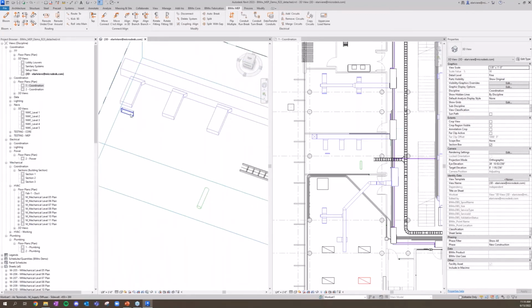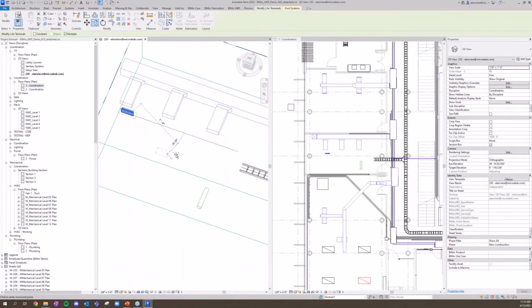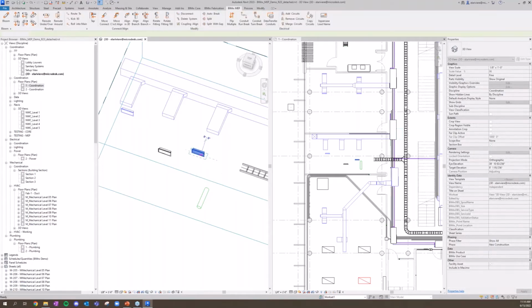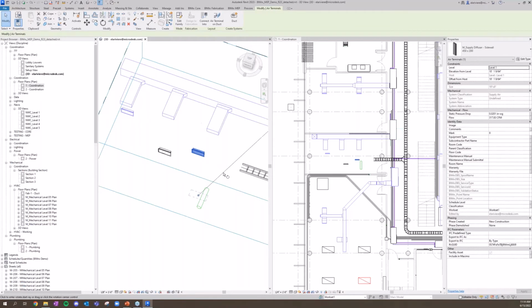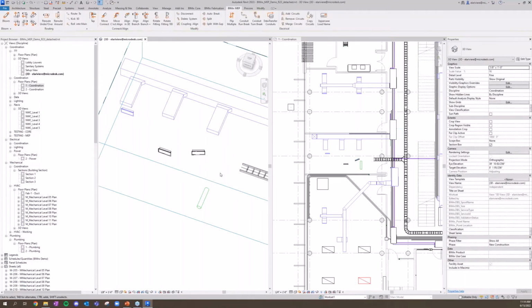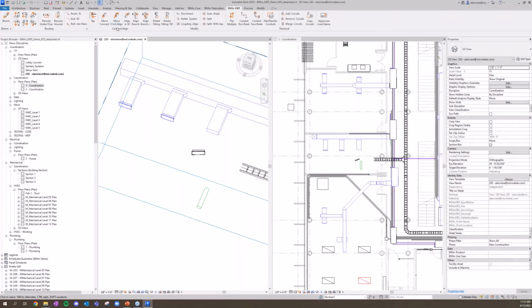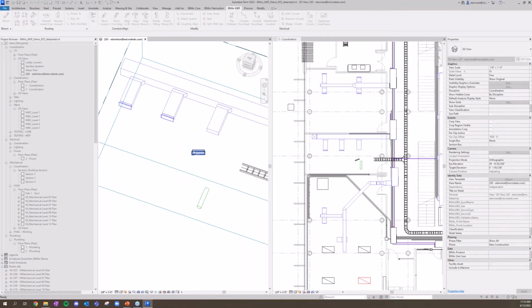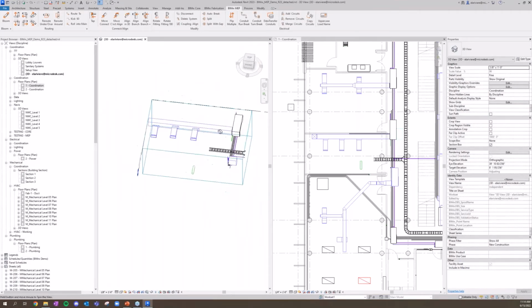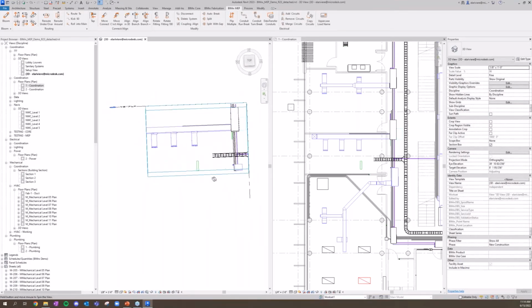My last step here, I've really got a few of these air terminals I need to connect. So let's go ahead and get a couple copies. And in fact, I'll even make it more difficult for myself and rotate one of them. We can use commands like move connect to immediately connect these pieces together. And then I can use commands like move connect align to cause a rotation and a connection on that. And there we go, that entire run connected together.